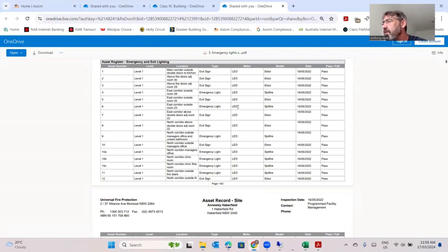If you haven't done our emergency exit light course, then you really need to do it for inspecting this, I believe. Even if you've gone through pathway 2, you'll need to do that emergency exit light course, because maintained LED lights have a requirement, essentially an expiry date or an LSL date. And that LSL date needs to be written on the schedule,